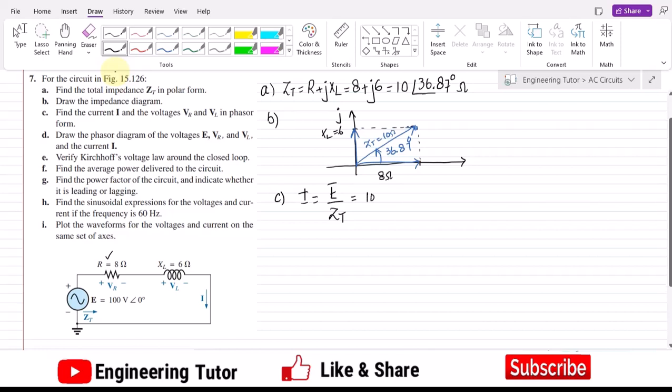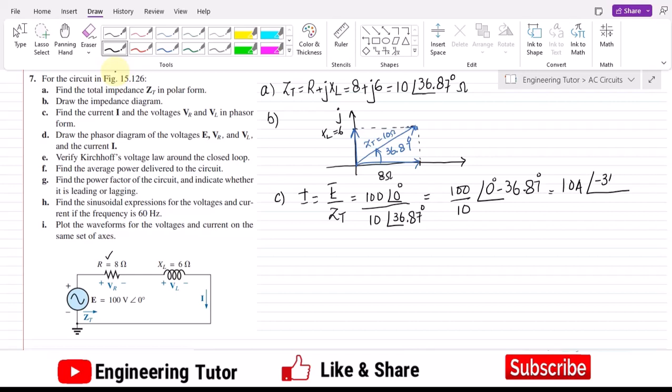Similarly, Zt is 10, and the angle it has is 36.87 degrees. Now it will be 100 divided by 10, and the angle will be 0 degrees minus 36.87 degrees, so it will be 10 amps, and the angle is minus 36.87 degrees.